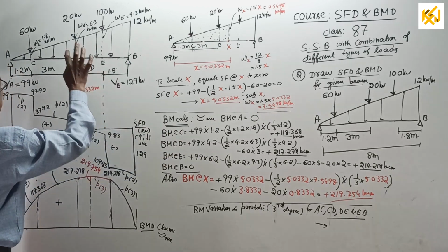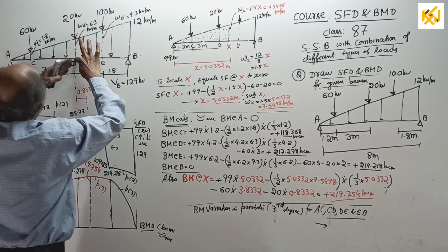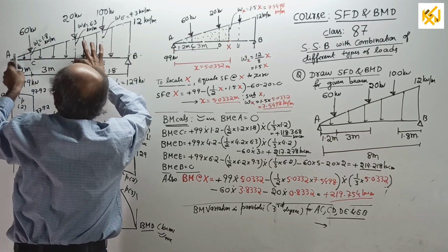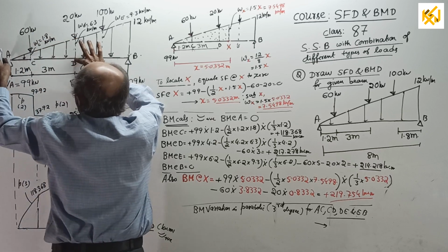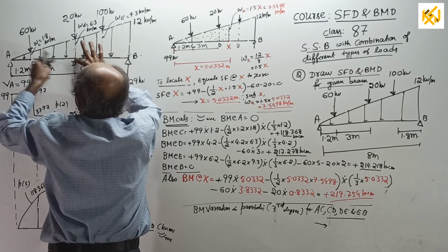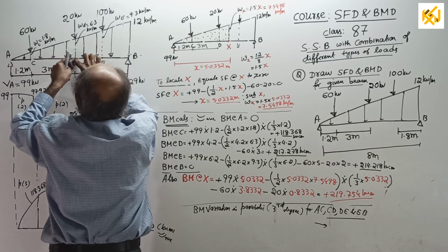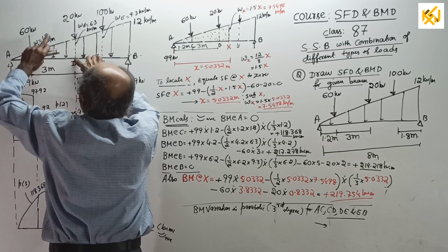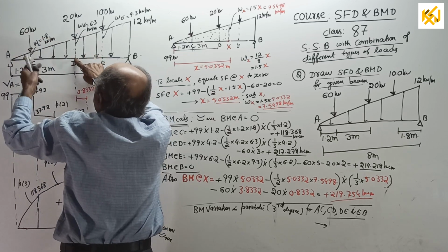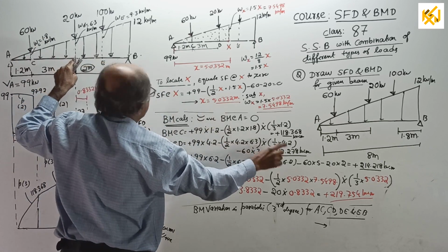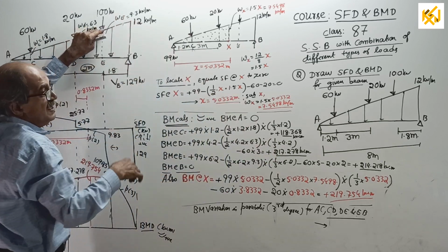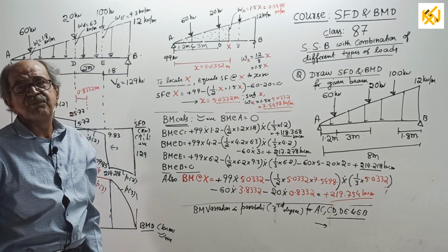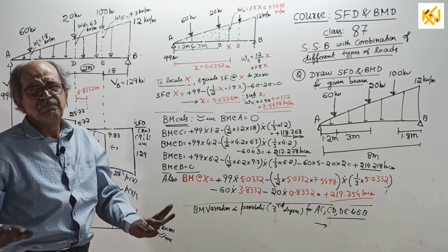I have written there. BM here. Look this side. Why? That side is trapezium. Plus 99 into 4.2 minus moment of this triangle load, half into 4.2 into 6.3 into 1/3 of 4.2. Lastly minus 60 into 3. You get the BM. BM here. If I want BM there, I will look that side. I am not afraid of trapezium, but still better look this side.